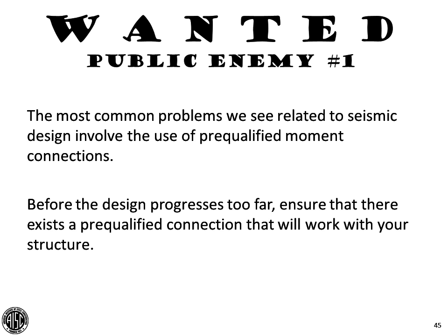Now, the last item we see come up fairly frequently, I'm calling it public enemy number one here, because it comes up pretty frequently, and when it comes up, it does seem to cause a lot of headaches for people. And it has to do with the pre-qualified moment connection. So if you're designing an intermediate or a special moment frame, then the seismic provisions require you to have physical testing essentially on these connections.